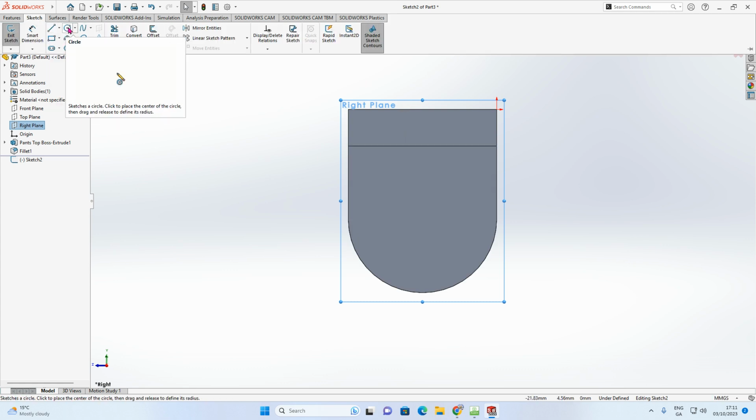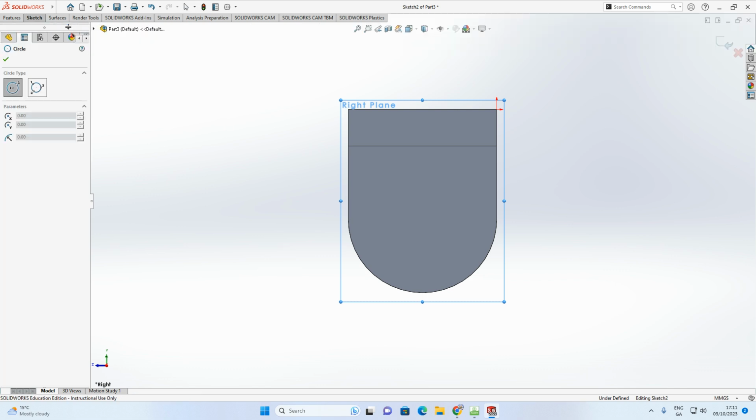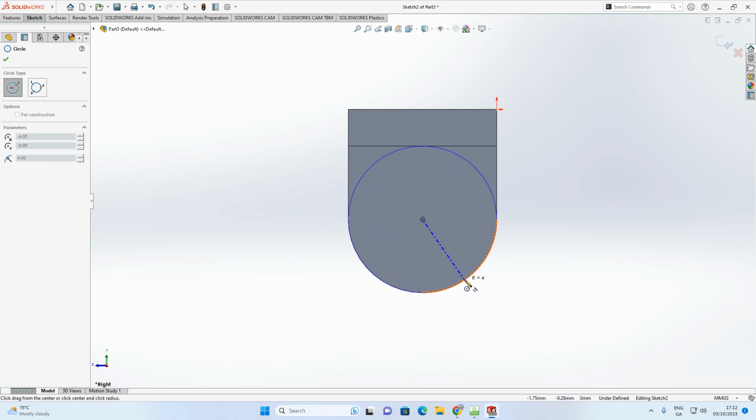I'm going to start off by doing a circle. Okay, select sketch tool circle. Now if I hover over this guy, hover over the arc, you can see the arc there. You can see it's prompting me to center point right here. Sometimes if you don't hover over it, you might have to find that, but I can hover over it there. It'll show me where the center is, and if I click anywhere around there on the center, it'll give me the exact center that I want.